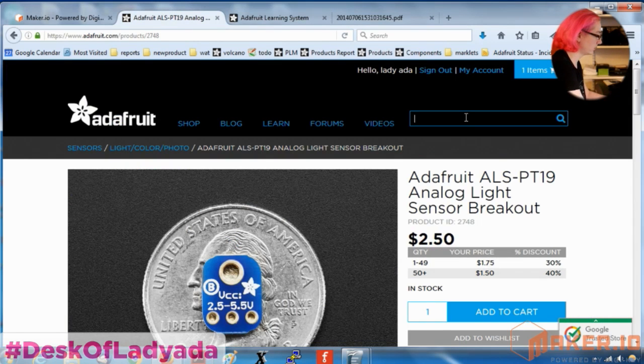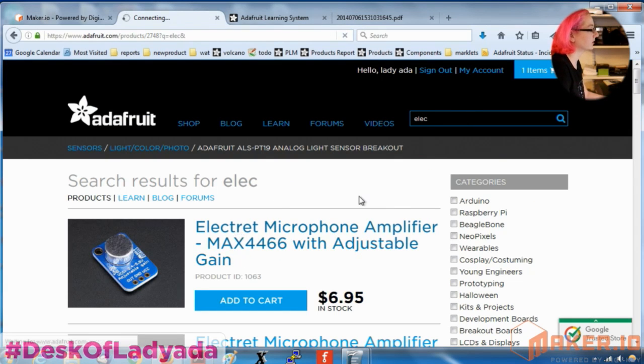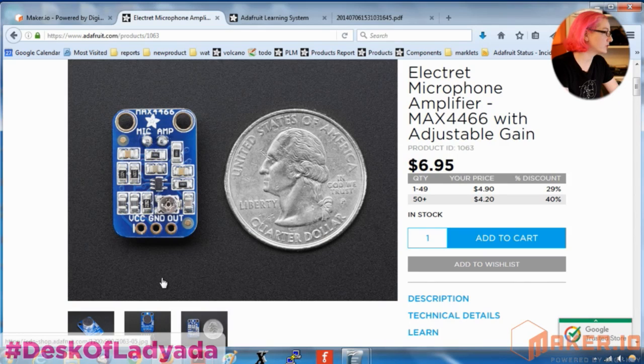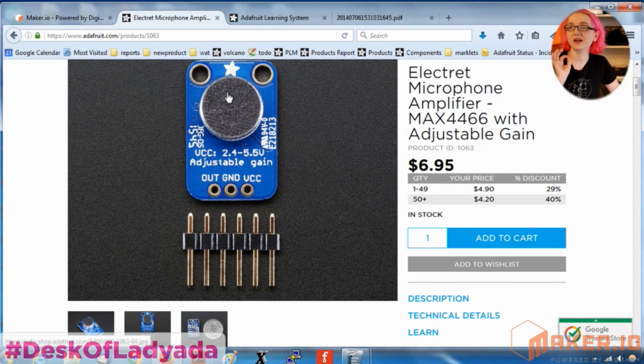So we sell in the store an Electret microphone, for example. And I was like, well, this is what I'm familiar with. But one of the issues with Electret microphones is that it's a through-hole part. And as a through-hole part, you still need to have an amplifier chip and all that good stuff, but you have to hand solder. And I decided I didn't want to have hand soldering be part of the requirement for the Circuit Playground First Edition, because our manufacturing line is pick and place. Basically, if you can get a part on a reel, it becomes very inexpensive to manufacture.